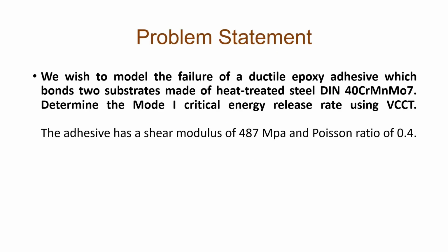The problem statement is so. We wish to model the failure of a ductile epoxy adhesive which bonds two substrates made of a heat-treated steel. And what we need to do is determine the mode 1 critical energy release rate using VCCT in ABAQUS.